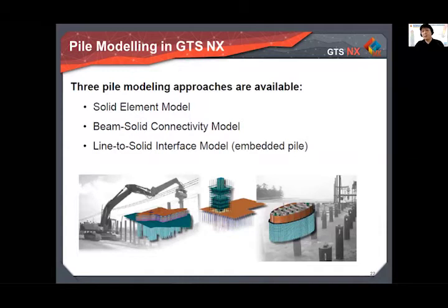So when we use the geotechnical software, in this presentation we are using GTS-NX from Midas, we can model piles with three different approaches. In general, in a 3D numerical model, you can simply consider the pile itself with a solid element, but sometimes it is more efficient to use only a line type pile element, for example if we have a pile raft foundation with a number of piles.